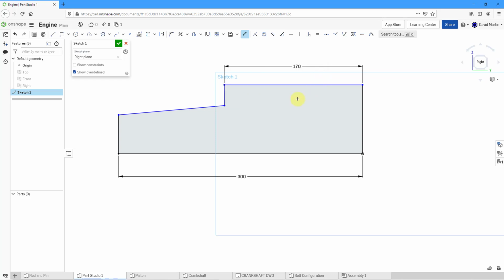And kind of ugly. Let me get this one from here. Did I get it? Left click. Okay, accidentally hit it twice. Left, left. And I want this to be a horizontal dimension with a value of 120. There we go. Now the line is back to an angle.